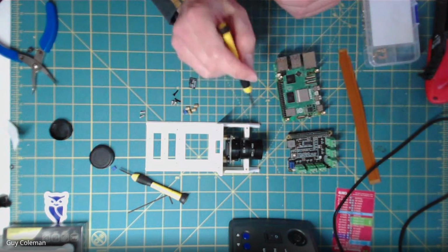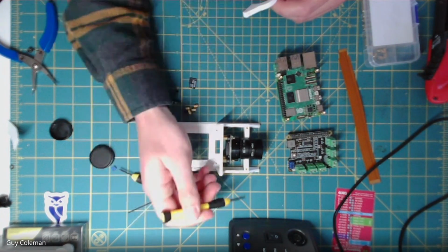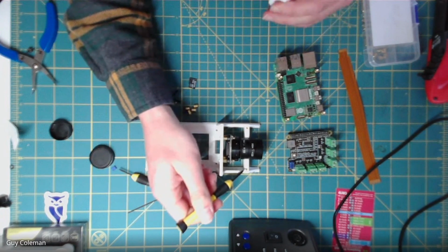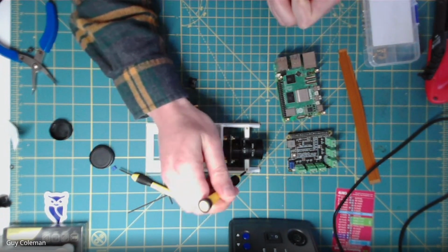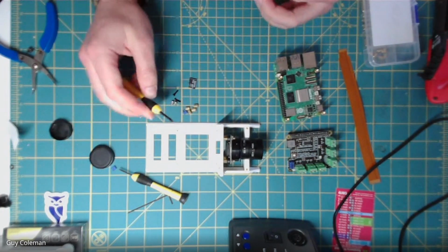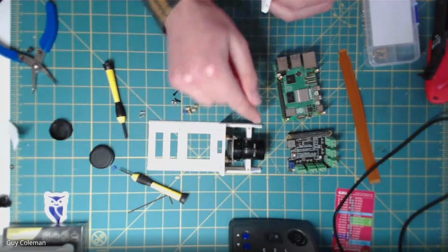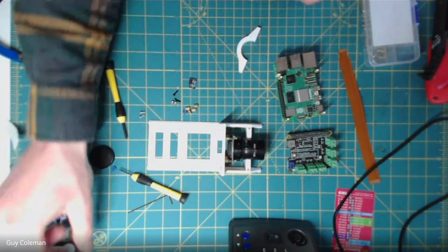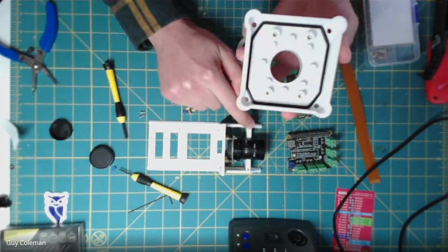So one other thing that I've added before are these heat set embedded nuts, or threaded inserts. What you have here are basically a brass insert. You use a soldering iron or something hot to press into the plastic, and then you can screw and tighten things down into it. You'll need 2 for the tray if you're using this tray and you want to lock it in place. You can also use them here, these are M2 size.